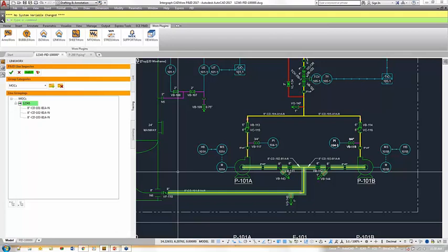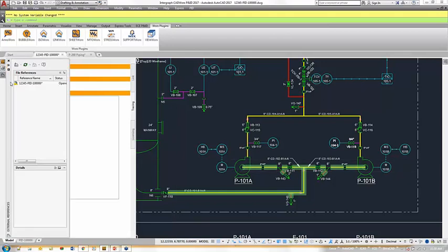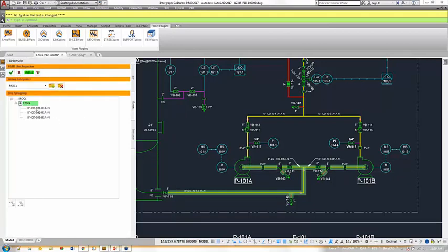So for example, if I have a line number that crosses multiple sheets and I have that as part of a group already, then that highlight's going to show up when I open up that second or third sheet with a header that runs across all drawings. We're keying off the tag, so as long as the tag exists in the drawing, we're going to highlight those lines if they're on. So part of it is turning on the highlighting.